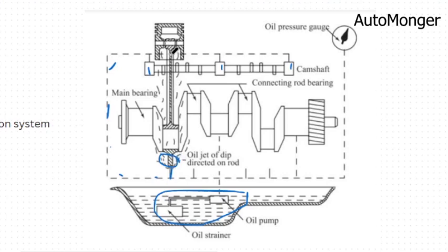So whenever the connecting rod moves through its own cycle and gets to this point, the splasher is going to pick up the oil and also splash it around all the body of this point where it is required. So this is an effective system. It's a combination of two systems, which is very effective. So this ensures that there's always oil every time.